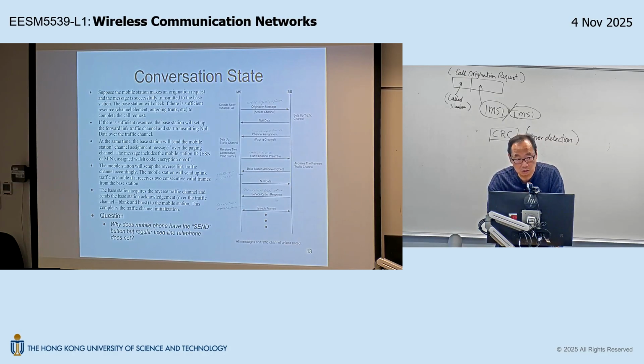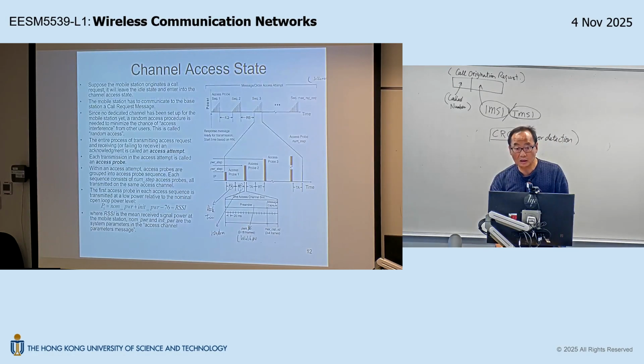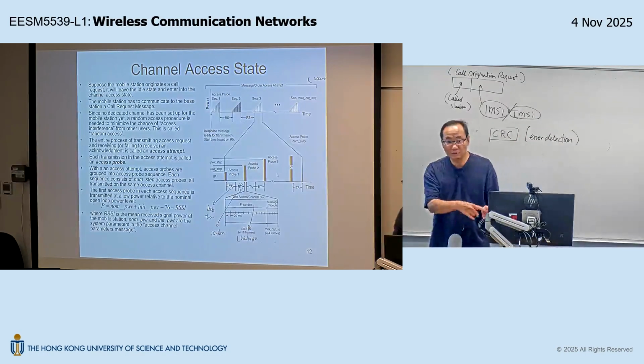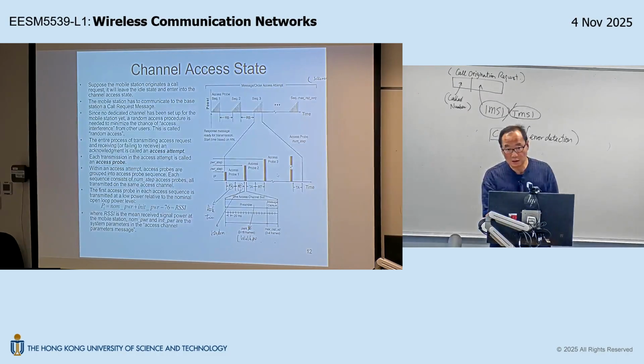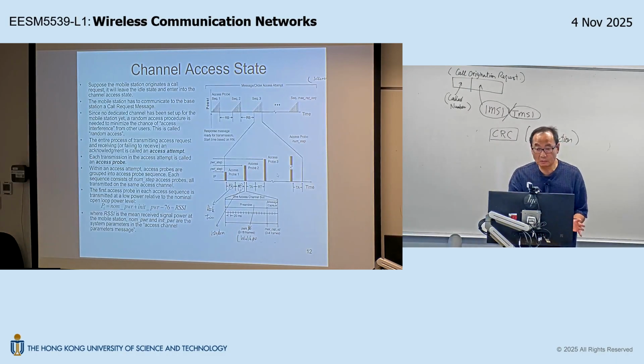The reason that the screen will flicker is because before the mobile phone actually rings, the mobile phone receives a page message. When the mobile phone receives a page message, it will leave the idle state and enter into the active state. So it will start to transmit this page response message with warm-up power. This transmission, because it's transmission from the mobile station, will generate EM interference. And this electromagnetic compatibility issue will interfere with your screen.